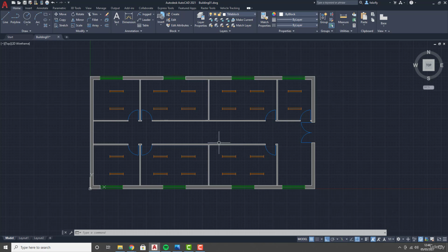And then we have everything here drawn to actual size, and this is known as our model space. So this is our model of our building, created to actual size in Modelspace. We've got the black background here, and if you look at these tabs, this one says model. So we are in the model space where everything is created actual size as per the real world. We also have these layout tabs. Now, ignore the fact there's 2 of them, okay? We're only going to work with one.